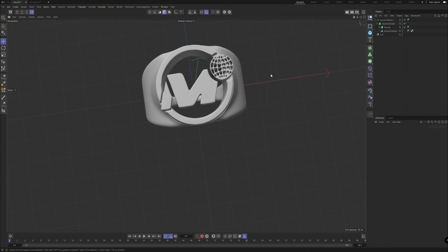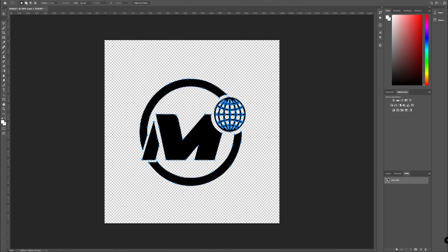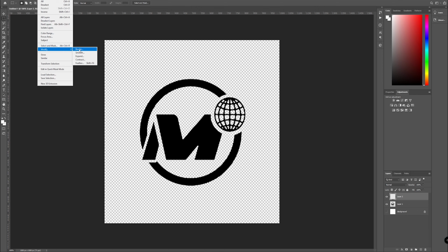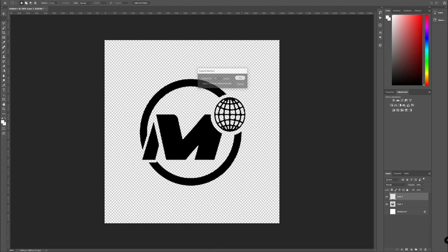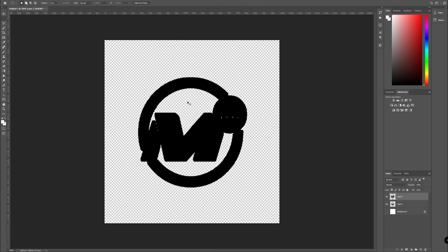So we'd want to likely, if we just take a second, what we could do is head to Photoshop, do a real quick technique to solve that issue. We could delete the work paths that are there currently. Take this, Control click, make a new layer, select, modify, expand. We can go 10 pixels, that kind of does the job. Fill that with black.